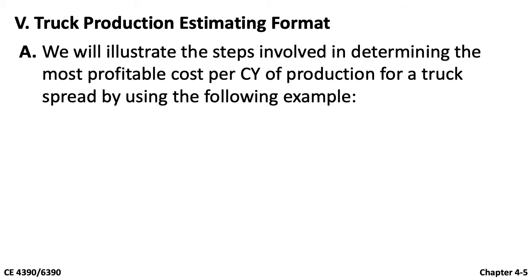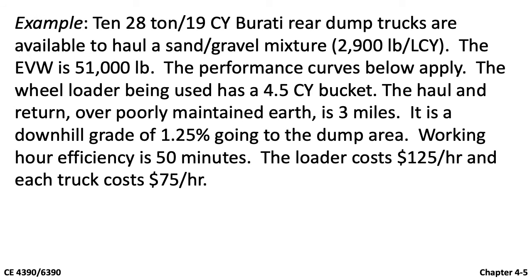Section 5, truck production estimating format. Now I'm going to show you how to estimate the production of trucks using the following example. In this example, we have 10 28-ton or 19 cubic yard rear dump trucks available to haul sand and gravel mixtures, which have a unit weight of 2,900 pounds per loose cubic yard, and the empty vehicle weight is 51,000 pounds.